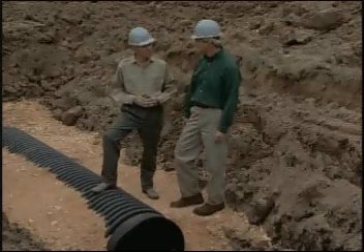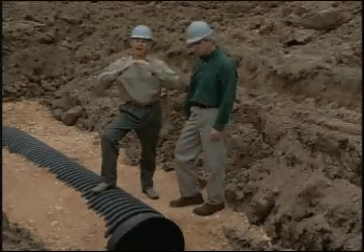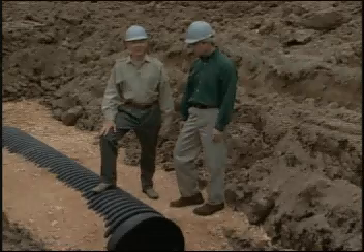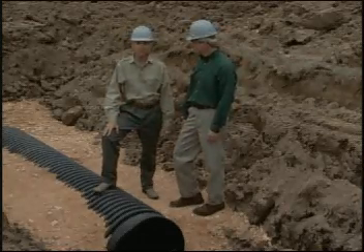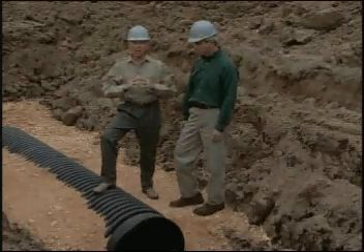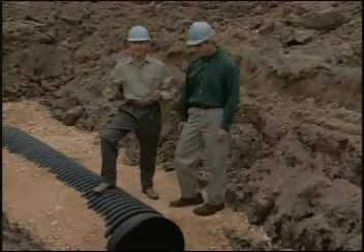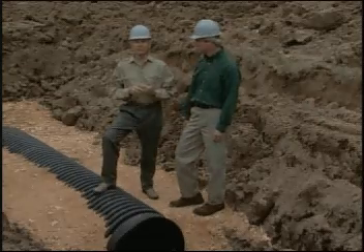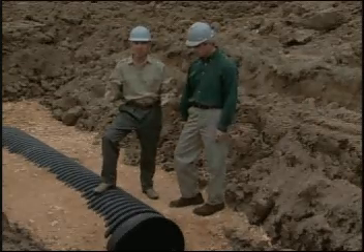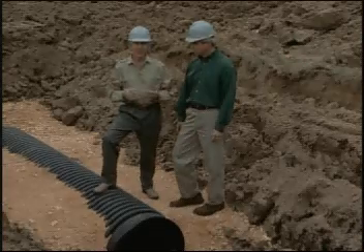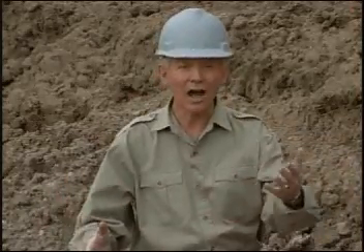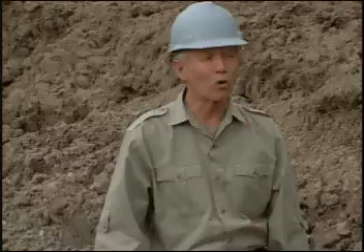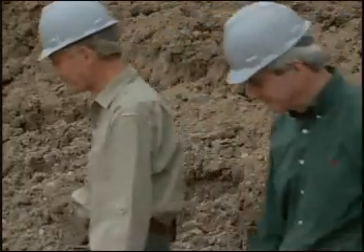Obviously, corrugated HDPE as well as CMP is flexible on the top as well as the bottom. The contractor can't forget to protect the arch in the wall of a flexible pipe. If that arch is lost or compromised due to bad practice in installation or subsequent soil settlement, the structure in the flexible pipe is lost. The Romans learned long ago that a flat arch does not work. The structure fails, the conduit fails. The only happy folks are the lawyers.